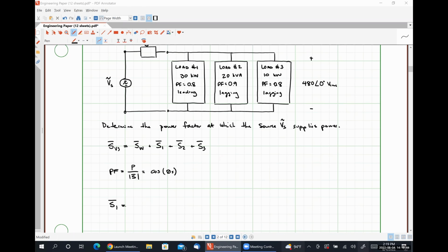So Devarier has suggested that the unit of apparent power is the watt. Unfortunately, he is mistaken. Average power is measured in watts, reactive power is measured in VARs, and apparent power is measured in volt amperes. Since this load is absorbing 30 kilowatts, that tells us that 30 kilowatts is the average power.